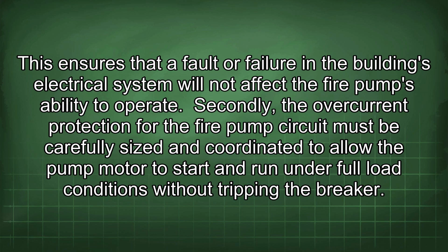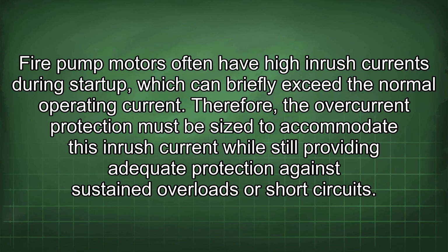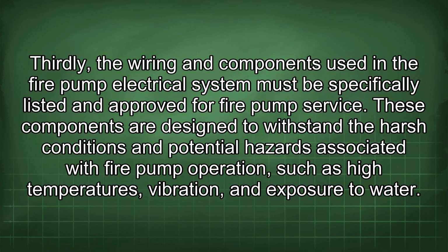motor to start and run under full load conditions without tripping the breaker. Fire pump motors often have high inrush currents during startup, which can briefly exceed the normal operating current. Therefore, the overcurrent protection must be sized to accommodate this inrush current while still providing adequate protection against sustained overloads or short circuits. Thirdly, the wiring and components used in the fire pump electrical system must be specifically listed and approved for fire pump service. These components are designed to withstand the harsh conditions and potential hazards associated with fire pump operation, such as high temperatures, vibration, and exposure to water.